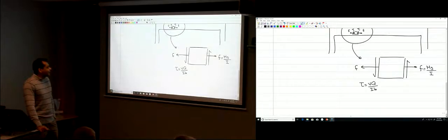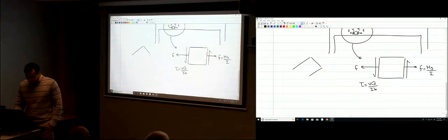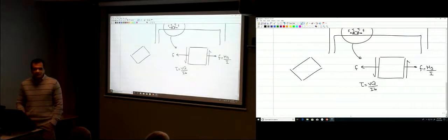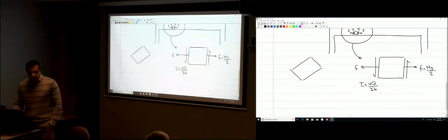So, how you have a shear force, you have a normal force on this plane. Actually, the maximum stress would be oriented at some angle. And that's what you call the principal stresses. The principal stresses are the maximum normal stresses that result from this, and it's going to be oriented by some angle theta.